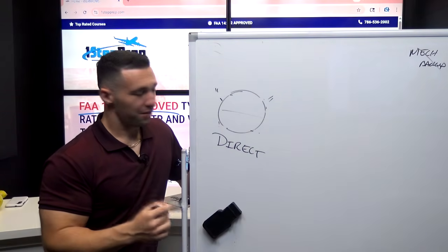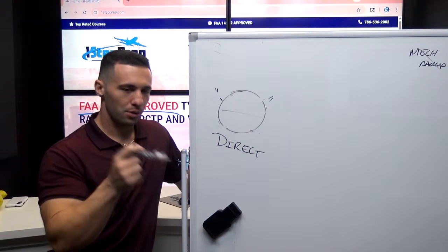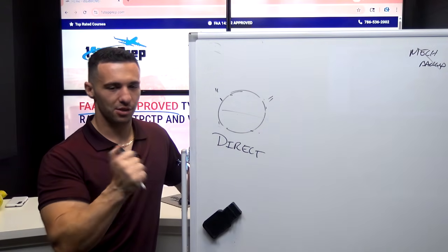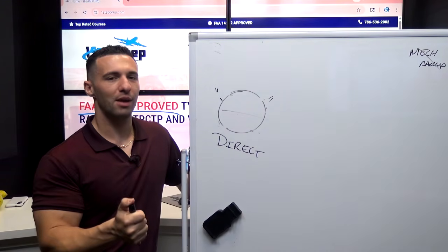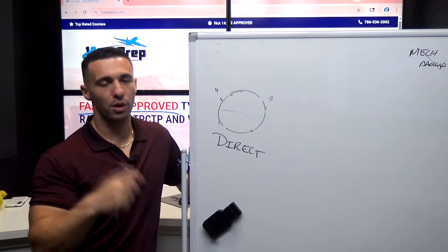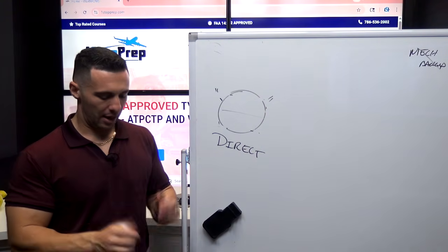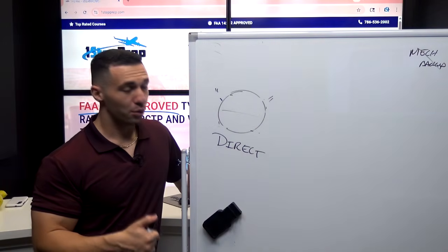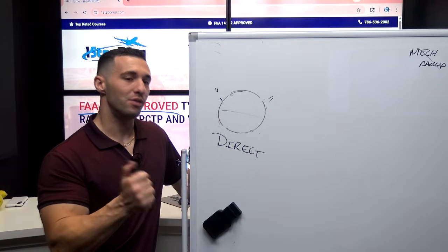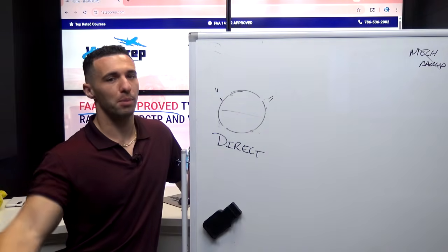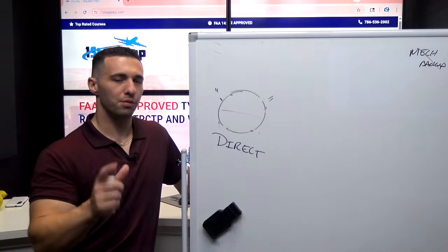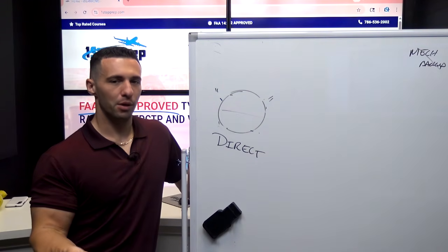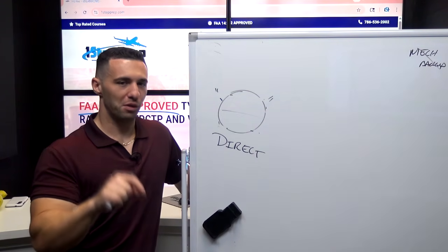And that's flight mode. Flight mode gives me G-load. The dominant characteristic of flight mode is that the side stick relationship changes to G-load and roll rate, and that is what allows you to have G-load protection, one of the variables, right? And that's also the reason, though, because you have G-load, that you need the following mode, which is flare mode. So flight mode is characterized by G-load roll rate, and the flare mode is there as a result of having